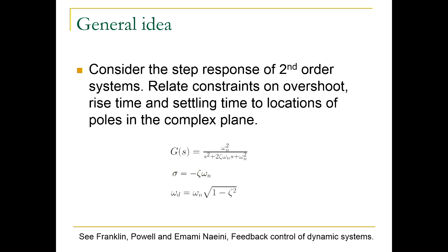Last lecture you talked about steady state errors. So how do we find steady state errors? We typically look at, if the system is stable, use the final value theorem. So s tending to 0 is important. So G evaluated at 0 is important for steady state errors. All right. So in this case, we assume that G at 0 is omega n squared divided by omega n squared. That's 1. Right. So that's a very special class of systems.